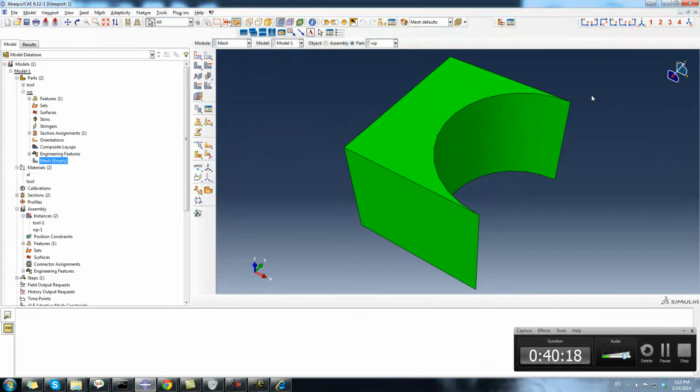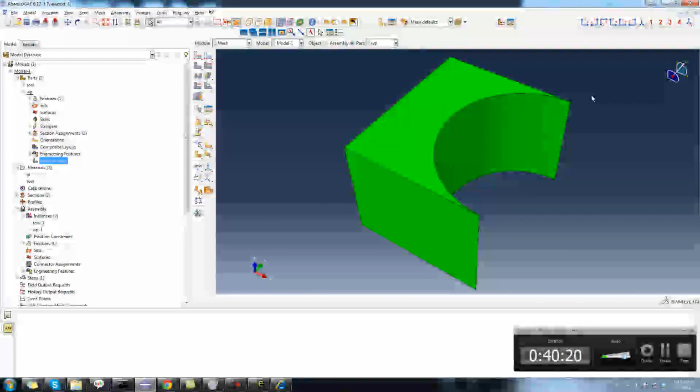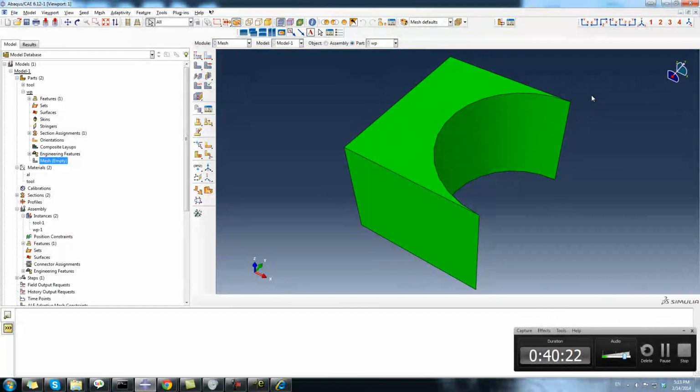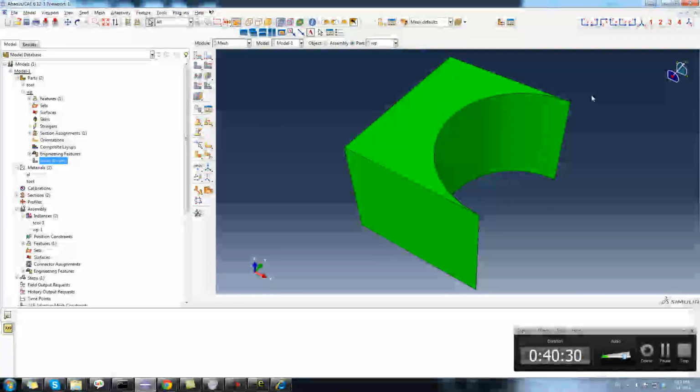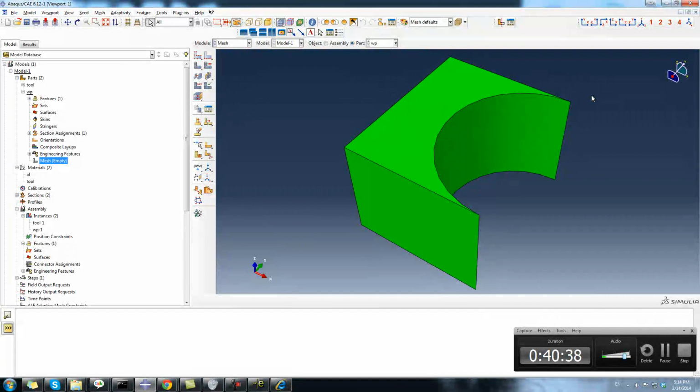one reference point on the tool, and we will combine this reference point with all the elements of the tool via a rigid contact. Rigid contact means it will not transfer stress and it will not transfer temperature. So no need to define another separate layer. Thermal conductivity will be zero, because no temperature can pass through the tool.